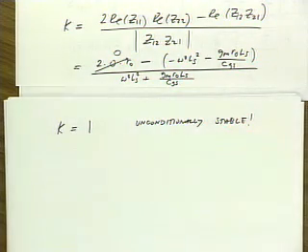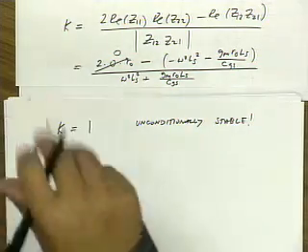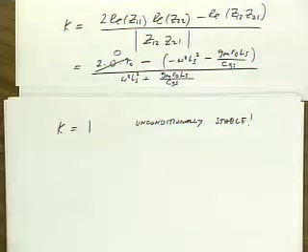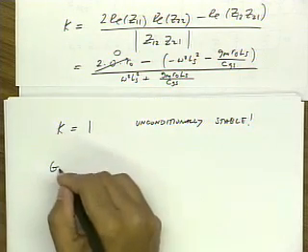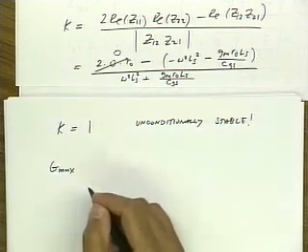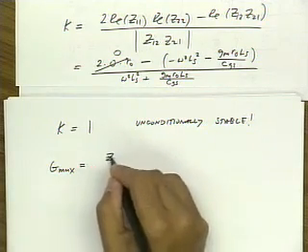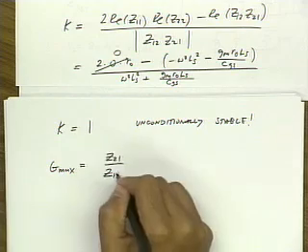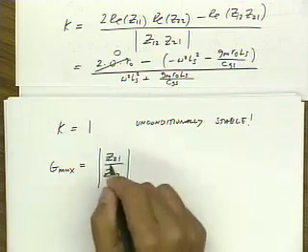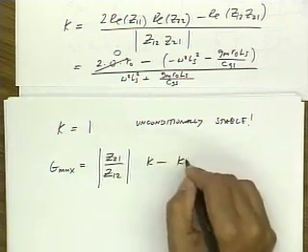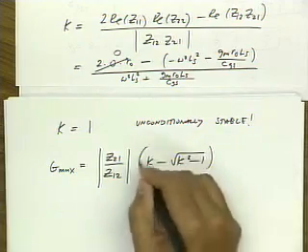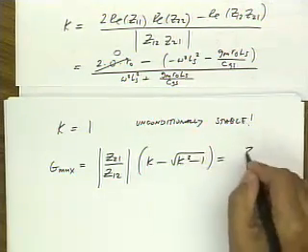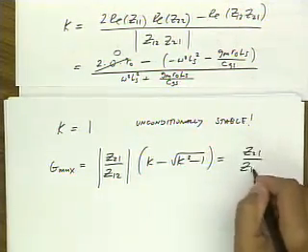That's actually pretty nice. It took our device, which was already unconditionally stable. We introduced feedback, but we found that this feedback could never make it actually oscillate. It's always going to be stable. So now if we look at the expression for the maximum gain we can get from this device, now I'm using Z parameters. It's Z21 over Z12, K minus square root of K squared minus 1. Well, K is always equal to 1 for this amplifier, so it's just Z21 over Z12.